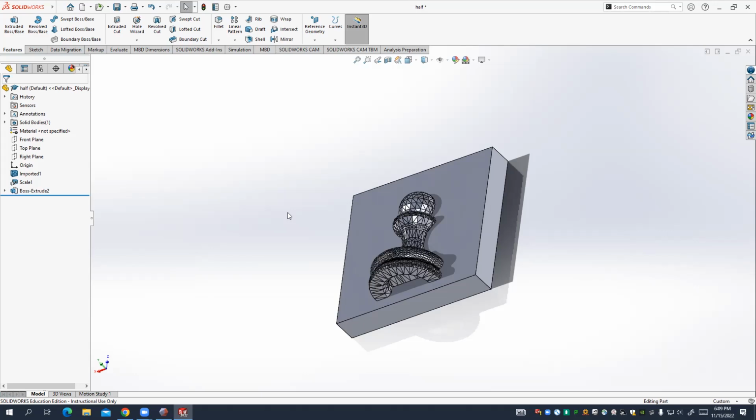All right, so the next step we'll do is we'll add our pegs and our holes. So if you look at any of the examples from last year's, you can see how you want to have pegs sticking out of one side of the mold, and you want to have matching holes on the other. So when you put the two halves of your mold together, they lock together, and you can strap them with rubber bands to make sure it stays tight. So we're gonna go ahead and add those now.